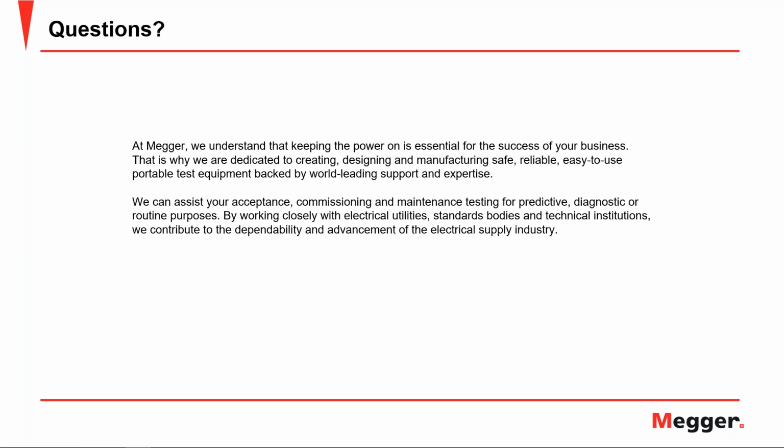However, it is important to understand that there are manufacturer specifications whenever it comes to these systems. So it's really important to understand what the application is from the manufacturer, because they may have a slightly different tolerance. However, in the absence of those tolerances, that's where these NETA standards come in, so that you have a guideline to go by whenever you're performing these types of tests.